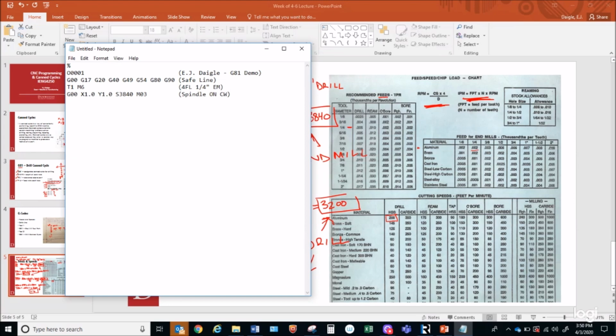All right, so now our spindle's on and we're ready to start cutting. Before we do though, we should always have a G43. If you remember, G43 is our tool length compensation. In this case, we'll give it height 1. This will be a touch off that you'll do with that tool so that the machine knows how tall that tool is. And we'll set ourselves up at 0.1 above the part. So I'll just call this tool length.